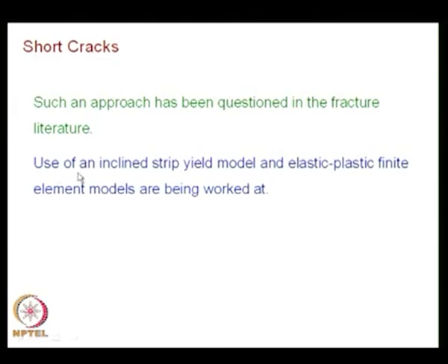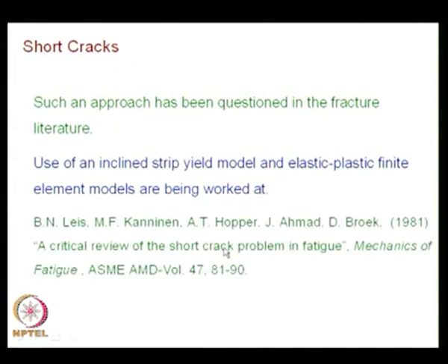and people are now paying attention to the use of an inclined strip yield model, and elastic plastic finite element models are being worked on to handle short cracks. And you can note down this reference. This is by Lees, Kaninian, Hopper, Ahmed and Broek, a critical review of the short crack problem in fatigue. Mechanics of fatigue, this is ASME AMD volume, which appeared in 1981, that discusses various methodologies.